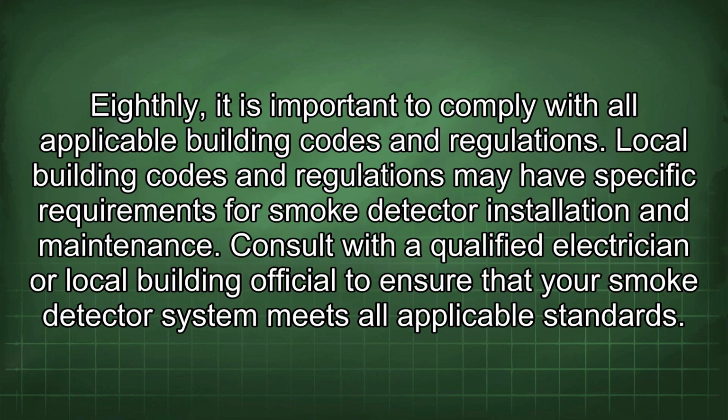Eighthly, it is important to comply with all applicable building codes and regulations. Local building codes and regulations may have specific requirements for smoke detector installation and maintenance. Consult with a qualified electrician or local building official to ensure that your smoke detector system meets all applicable standards.